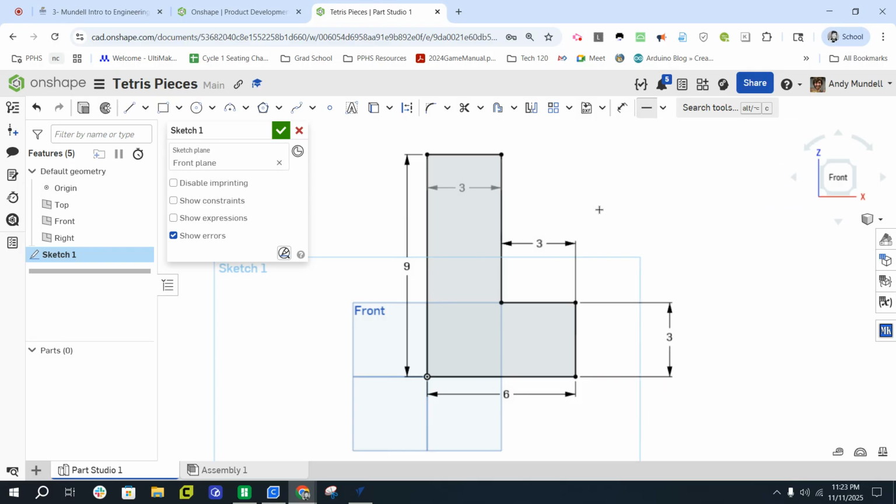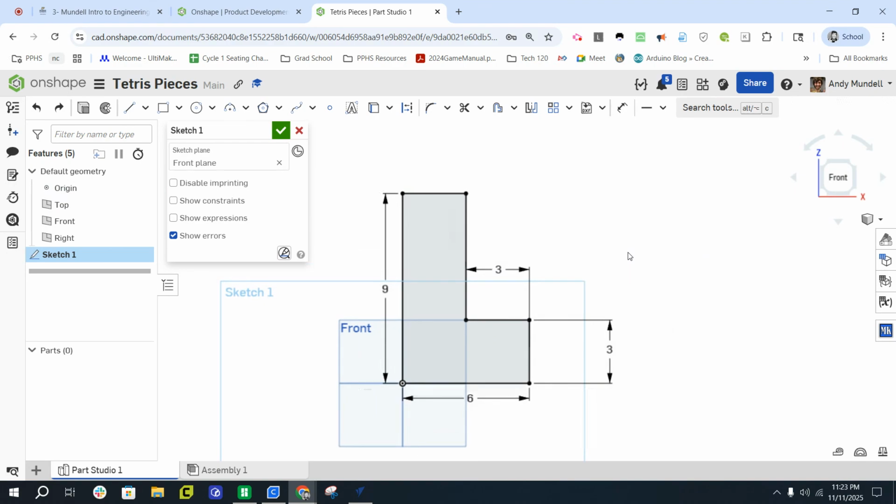Okay. Sometimes you'll dimension something or over dimension it. Let me see if I can find another one. Maybe I dimension an angle. So to dimension an angle, I can click one side, and then I can click the other, and I can go right here, and I can say I want that to be 90 degrees. Ooh, now it went red. So it goes red when it says, hey, you've put too many dimensions on here. There's too much stuff going on. So let me undo the last thing I did. And I can take those off. I don't need to overlay dimension.